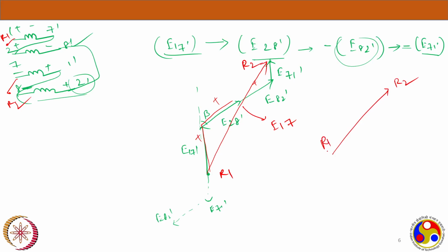Now if you do the similar kind of phasor for Y and B, you will get similar ones, maybe here, if it's an RYB phase sequence. So this is Y1, Y2, B1, and you can see the displacement of phasors. This is the R1 R2 resultant. This is Y1 Y2 resultant. This is B1 B2 resultant. So this is how you get the phasor distribution in space, and in each phase you try to extract as much voltage as possible.